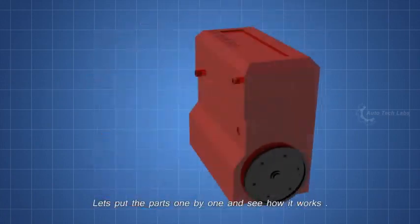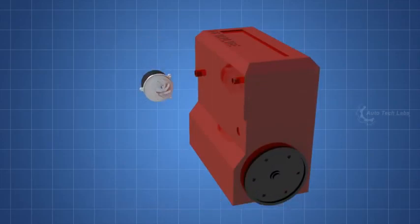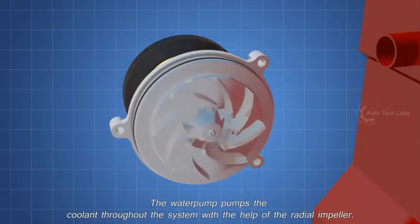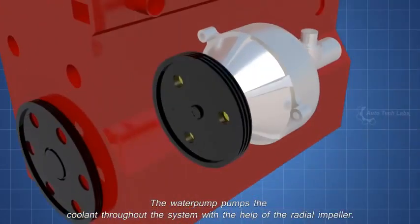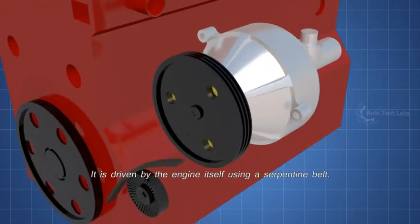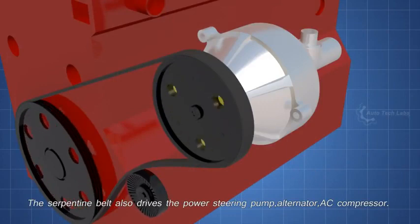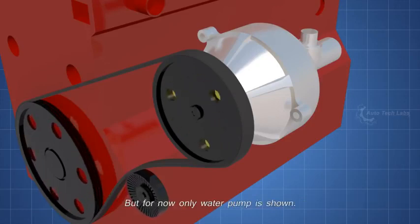Let's put the parts one by one and see how it works. The water pump pumps the coolant throughout the system with the help of the radial impeller. It is driven by the engine itself, using a serpentine belt. The serpentine belt also drives the power steering pump, alternator, AC compressor. But for now only the water pump is shown.